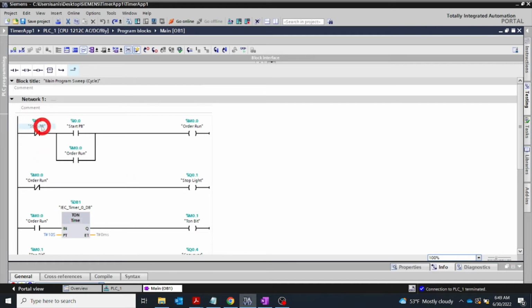This is port input 1 for the stop push button. The start is on port 0. These are internal bits, which I showed you how you could make, which we call overrun. And this one here is the normally open, which is controlled with this one that you have.